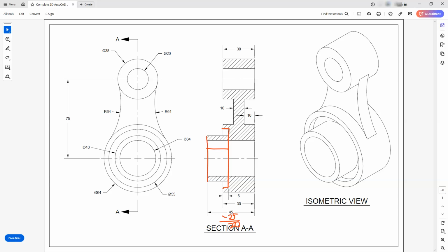We're going to create it on this face, and then we're going to extrude it going this direction. If you want to refer to the drawing over there, what's the diameter of it? We're going to find that the diameter is sitting here at 43. All right, so let's jump back over to Inventor.